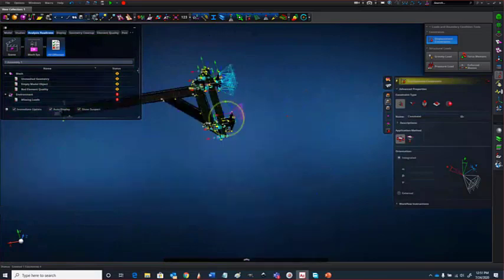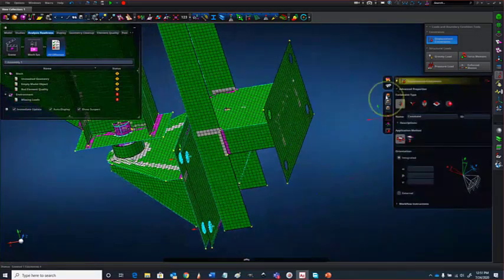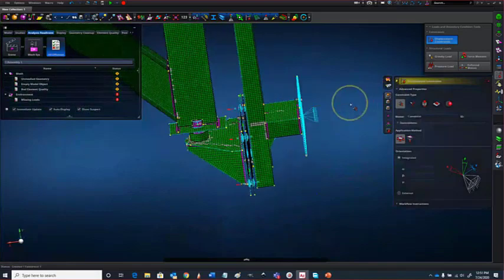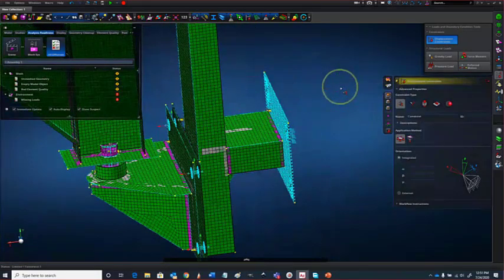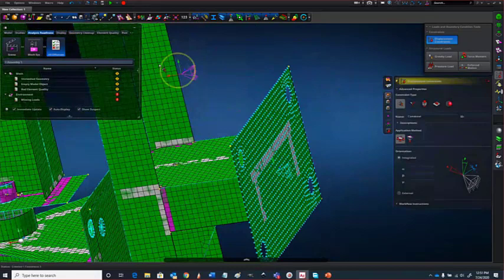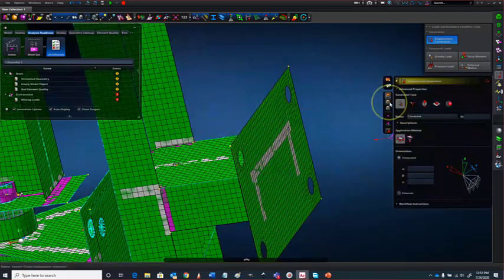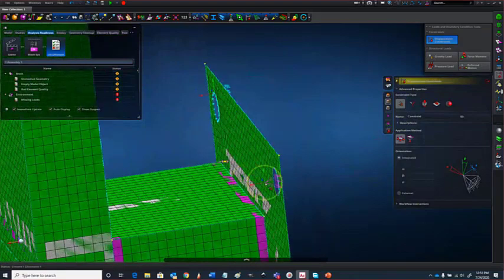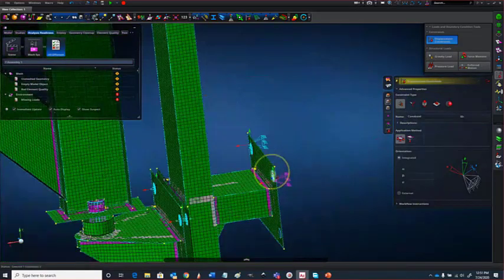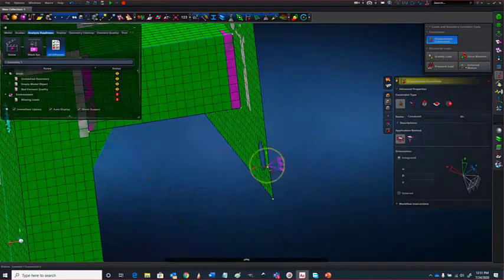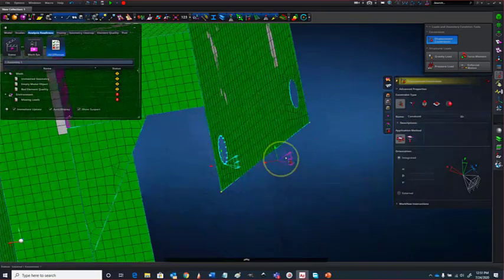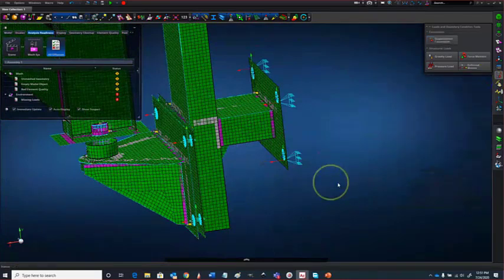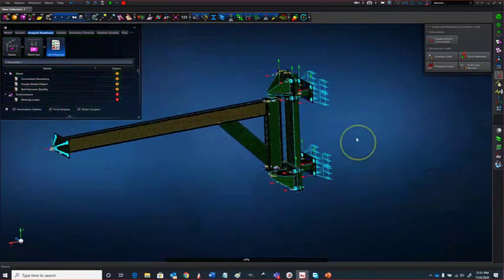Or if it attaches to a very stiff component, we can just connect everything at once, although it's generally not necessarily the best idea because it could be over stiff. So I'll just rather use this option as if there's no backing support. Okay, so now everything should be fine.